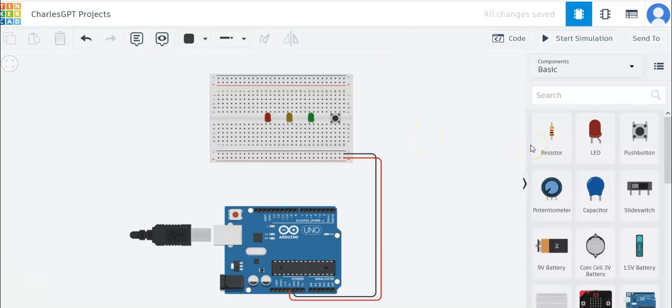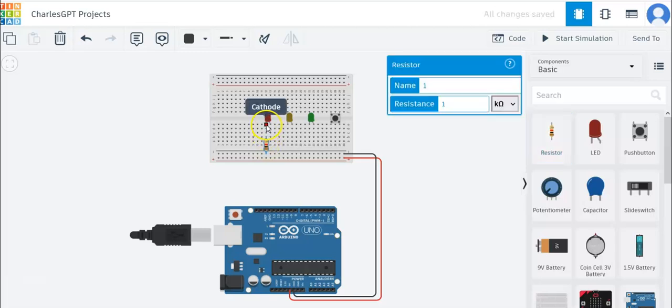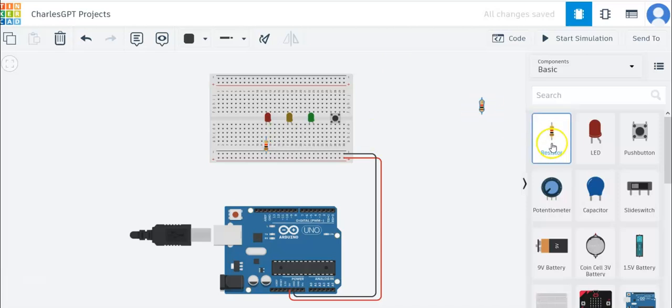Then you need resistors for every single thing you're doing. The resistors must be connected to the negative sign. Since we have 4 components, we need 4 resistors. It doesn't matter about the resistor values or things like that. Then I'll just connect it. So for the LEDs, the resistors will be connected directly to the cathode and the negative. Anode is for the main connection, then cathode is for the resistors. No need to check the resistance, it's just anyhow.